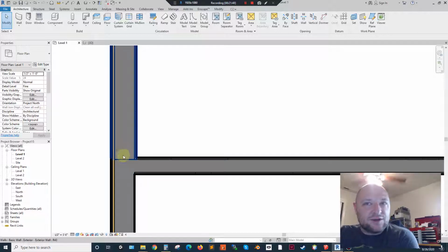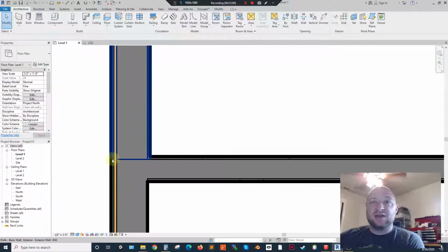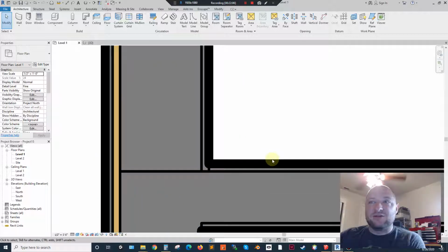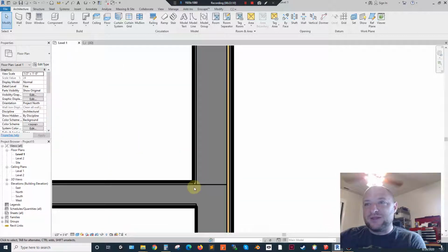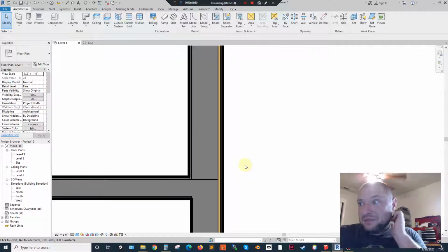Now, it's not joining these together, and the reason why it's not joining these studs for the interior wall and this unfinished garage is because this section actually has the bad insulation. So Revit is recognizing that material difference and not drawing this line through, whereas here you can see it's drawing the sheathing and the exterior finish. I don't know why it's not caring about that though, that's weird. Should be joining the gypsum, it's not. I'm not too worried about it.